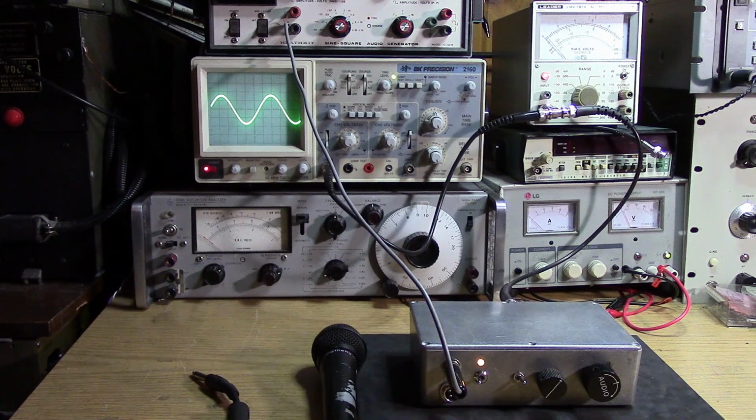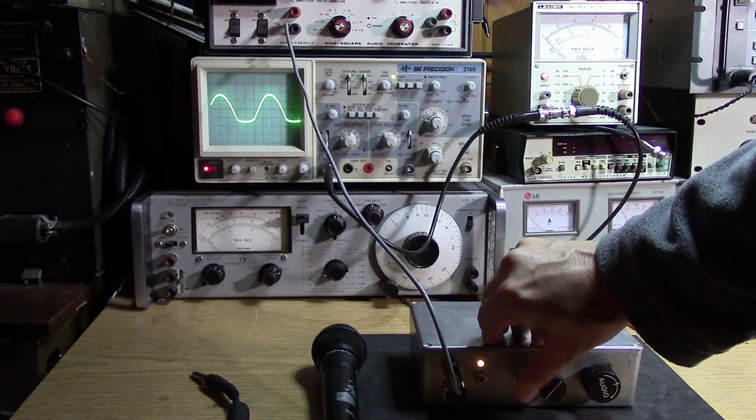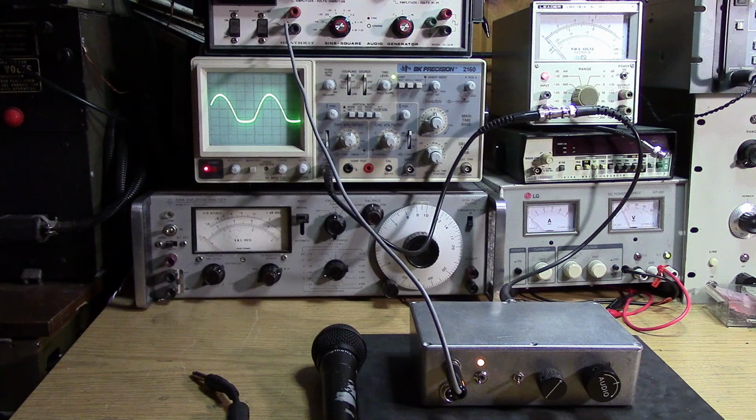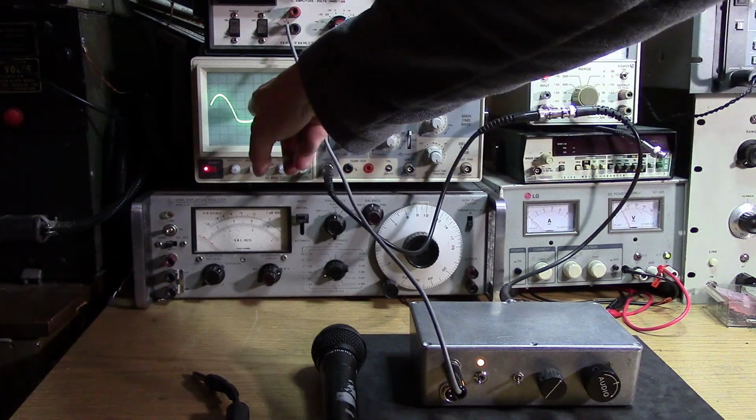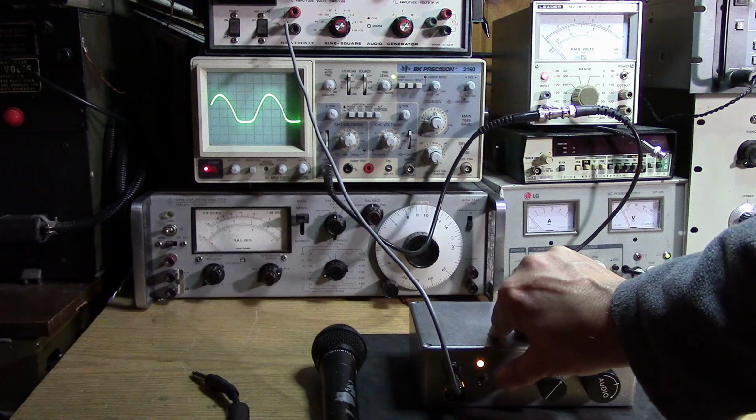Okay, I've got a net going in the background, but let's take a look at the speech processor with a 1 kilohertz sine wave. Now let's look at putting in the clipper, and as you can see with the clipper, we definitely are lopping off some of the negative peak. Now if you wanted a more drastic cut, instead of using silicon diodes, you'd use Schottky diodes, and that would bring this up, of course, a little bit higher on the waveform. I just wanted to show you what it's like when you cut in the clipper.